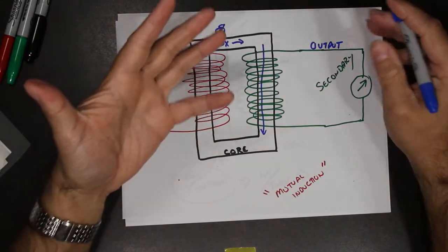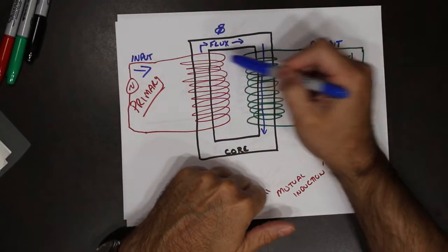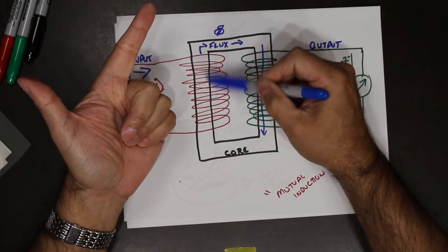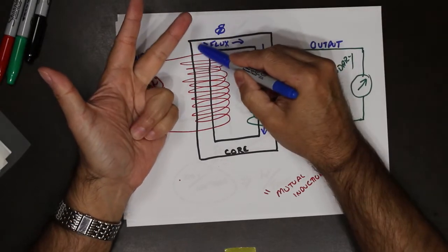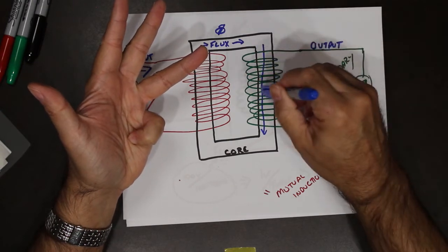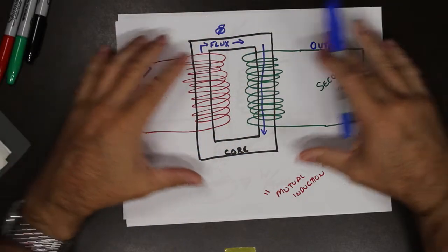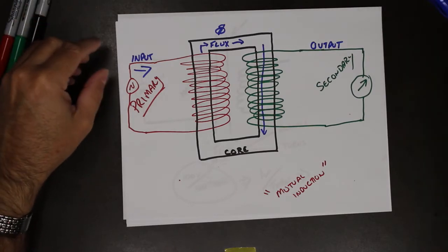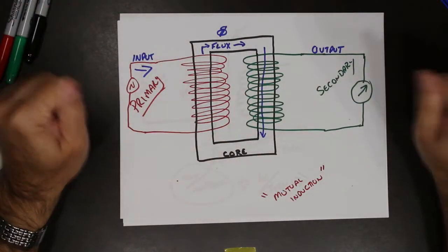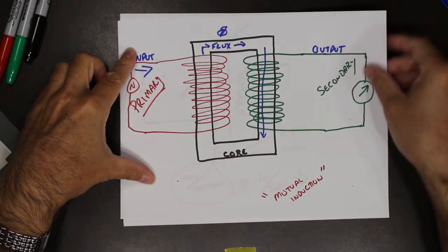Five. So in general, we can look at 5 different areas of loss. Again, resistance of this coil, resistance of this coil, transferring the magnetic field that's been created here into the core, losses in the core, and then transferring the magnetic field back into this coil to get our voltage. So 5 areas of losses. For this course, the majority of the work we're going to be doing in our discussion, we're working with an ideal transformer. So we're going to say there are no losses in the system. Everything is perfect. But in real life, there are 5 areas of loss.